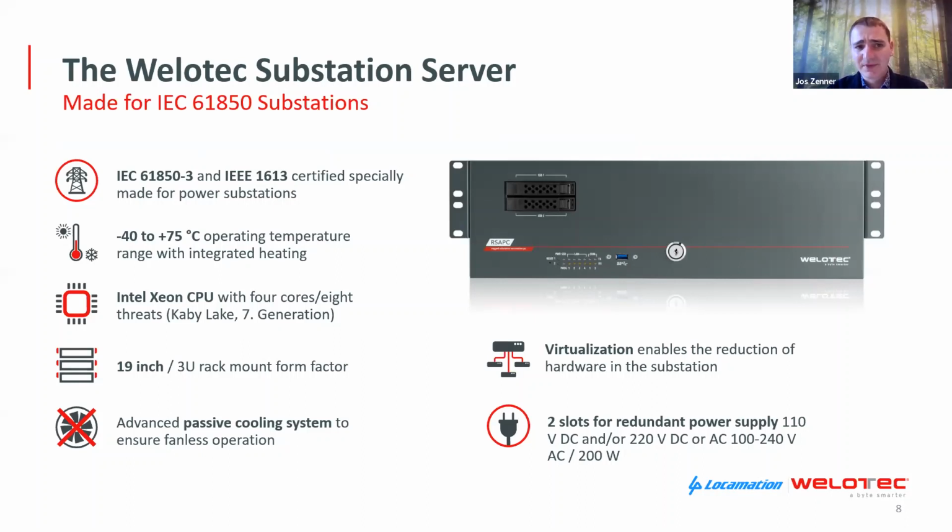It is fully IEC 61850-3 and IEEE 1613 compliant, which means temperature ranges from -40 to +75 degrees, very high EMC levels, and very good resistance against vibration and shocks. So it can operate under all conditions.